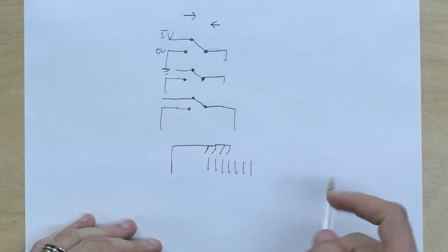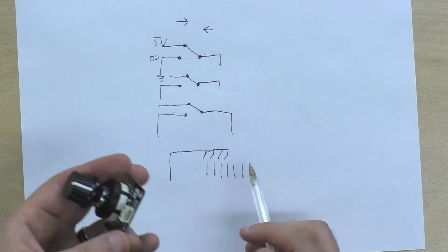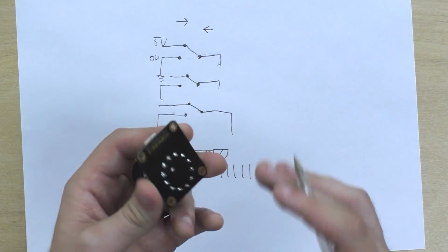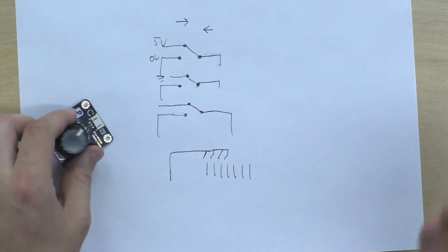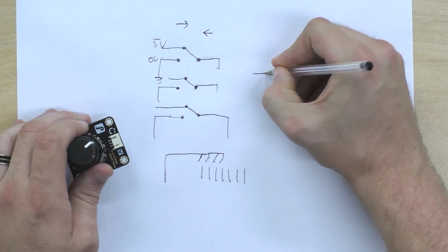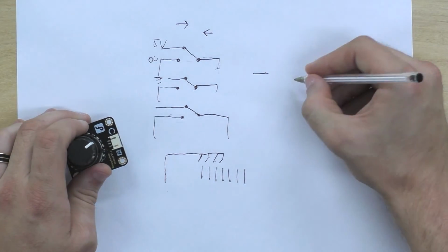You've got another type of switch like this, and these ones are designed for analog input to microcontrollers, because instead of having lots of different outputs, you can see it's got a connector for a sensor cable here by DF Robot, and it only has 3 pins. So, how do we get that? Well, what happens is it utilizes a resistor ladder. So we have 1 input here, all right? And then there's a bunch of resistors.